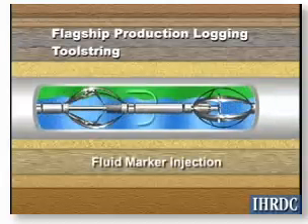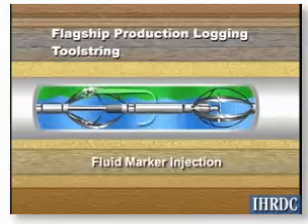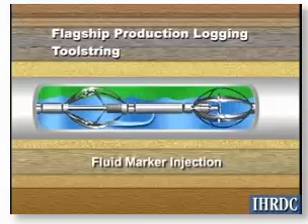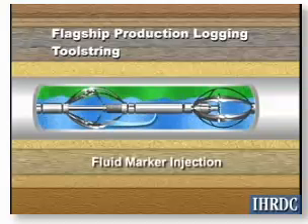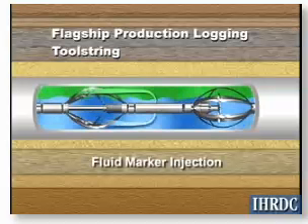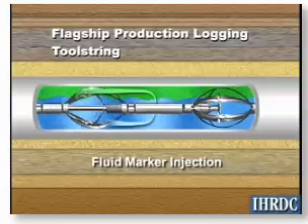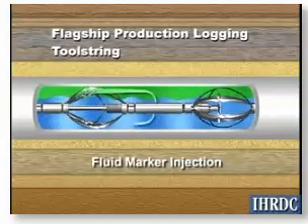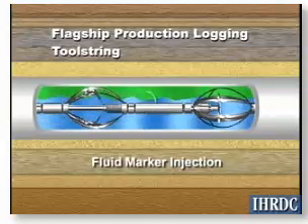The tracer method uses special liquids that are designed to mix only with the water phase or with the oil phase of the production stream. The tracers contain gadolinium salts, which produce high gamma ray counts when irradiated. In the horizontal wellbore, the oil tracer and the water tracer are ejected into the production stream by the fluid marker injector, where they mix with their respective phases.